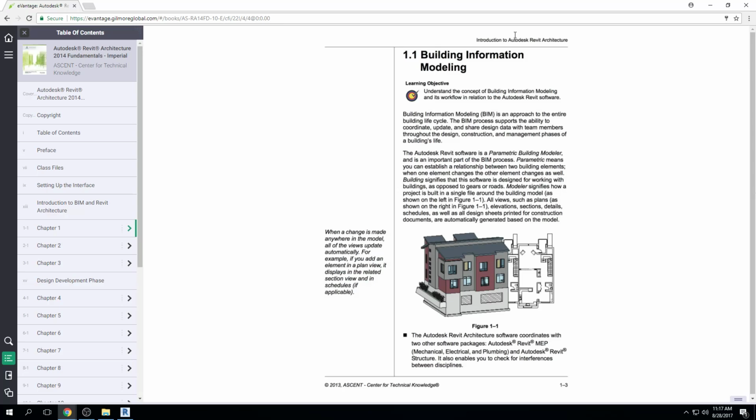In Revit, the way that we work is we have several people in one model at the same time, and information is sort of simultaneously checked in and out as you save back and forth, right? So I can be working on the floor plan view of my model, and somebody else can be working on the floor plan view of the model, okay? The items I touch can't be modified by my second person, but when I save, my connection to those items is cleared out, and that person can then engage those items, right? So it's kind of a checkout system that you use in Revit that is cleared every time you save, okay? Now that's if you have multiple people working in the model, okay?